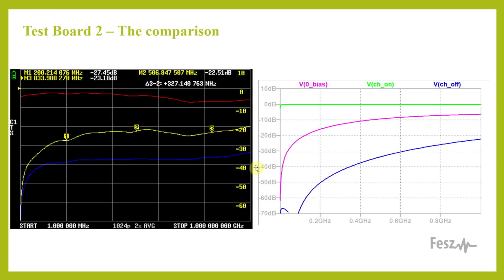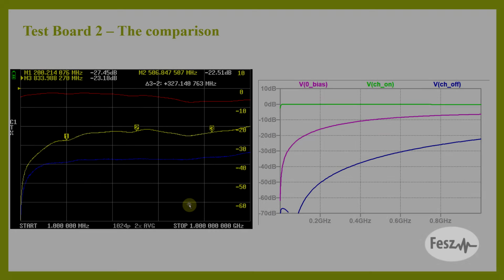So there are some deviations in between the simulation model and real life. Things like the biased inductors were not properly modeled and no transmission line losses were considered, but regardless, the switch does work, even if it needs a bit of fine-tuning.